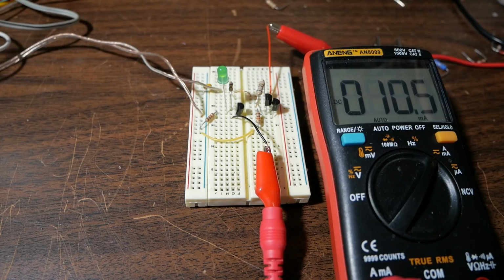We're at 4 volts, and it's changed a little bit. And I'm going to keep dropping it down to see where its dropout voltage is. So we're at 2 volts now. We're at 1.5 volts. Okay, it's dropping out now. That's 1.2 volts. I'll bring it up. 1.3.